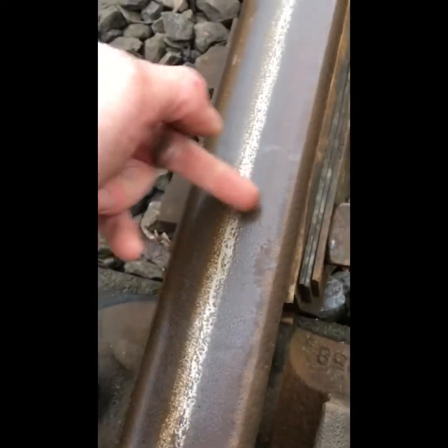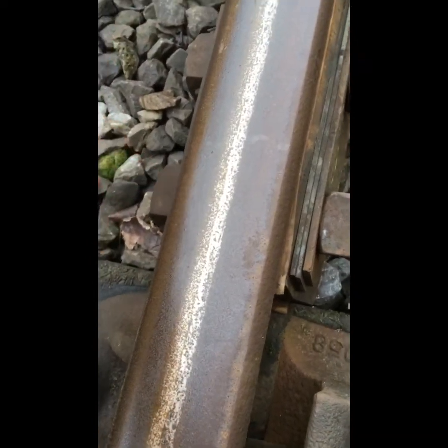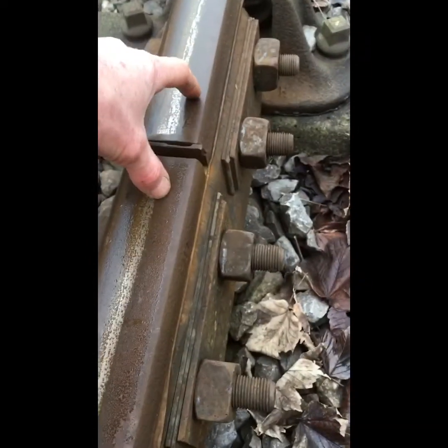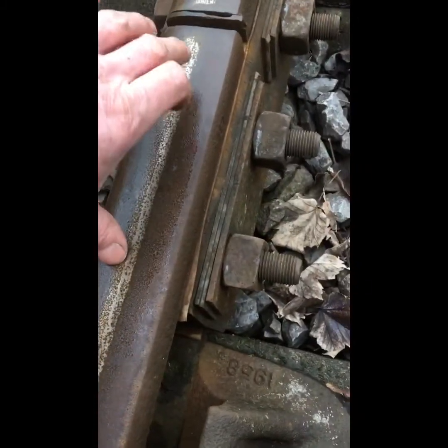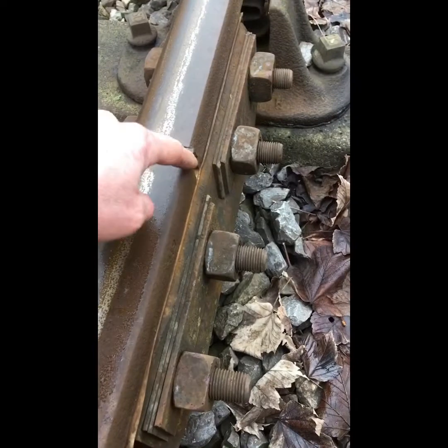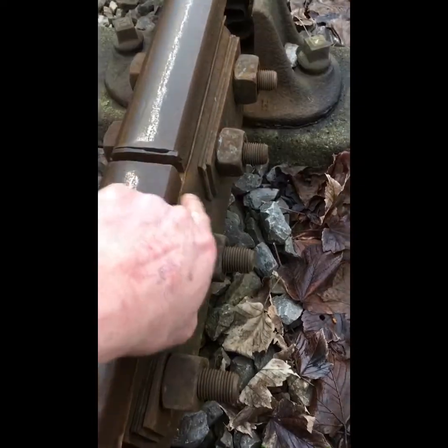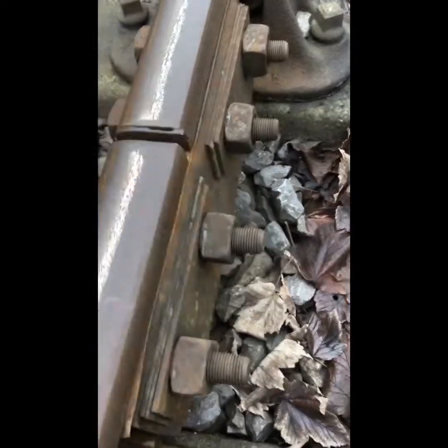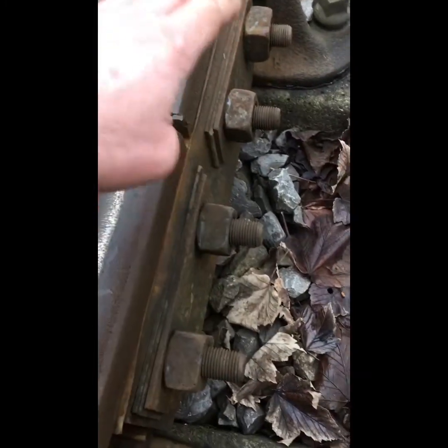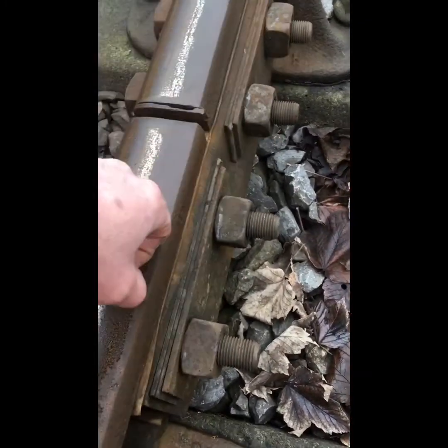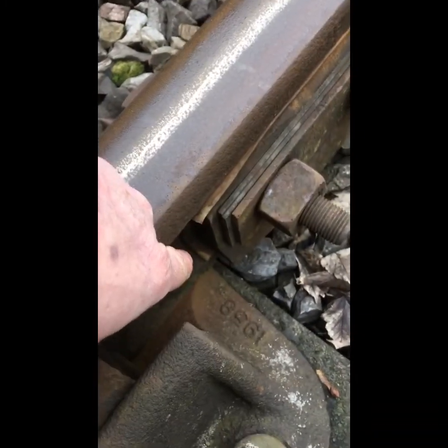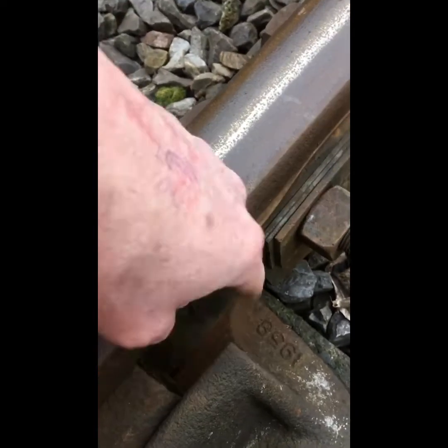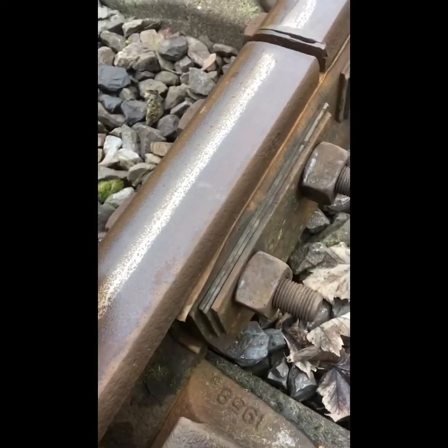So when the PUA comes to knock the bolts in, they should be extremely careful not to just hammer them in. If the rails are slightly wide, it's not a great idea, because you'll just strip the insulation off and drop the track circuit. Likewise, if you're cutting rails, you ought to make sure that all the swarf is gone before you put the plates on. Nowadays they have a magnet to drain all the swarf off before they put the side plates on, and you want to make sure that plates don't drift too far and end up catching on the chairs themselves, because that can also cause problems as well.